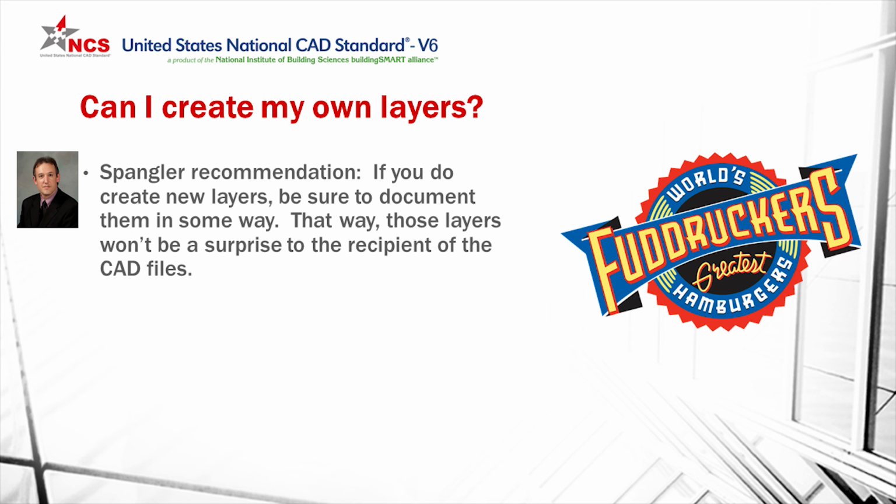Now, what's going to happen if that person runs some sort of checker and they have all the National CAD Standard layers programmed into this? Immediately that layer is going to be flagged and they're going to say, hey, you're non-compliant. And they're going to throw the drawings back at you and say, please explain this. So a good thing to do is, if you do create new layers, be sure and document that somehow and provide that along with the drawings so it will not be a surprise to the recipient of those drawings.